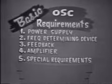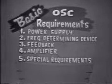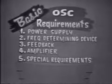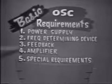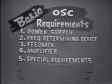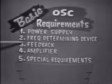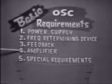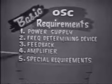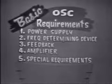There may be other requirements depending on the application of the oscillator, which you'll discover when you study a particular piece of equipment. But the main idea is that all oscillators are basically the same. So whatever the type or the name of the circuit, all oscillators will require a power supply, a frequency determining device, feedback, usually from an amplifier. Now, if you apply these basic principles, oscillators will be much easier to understand.